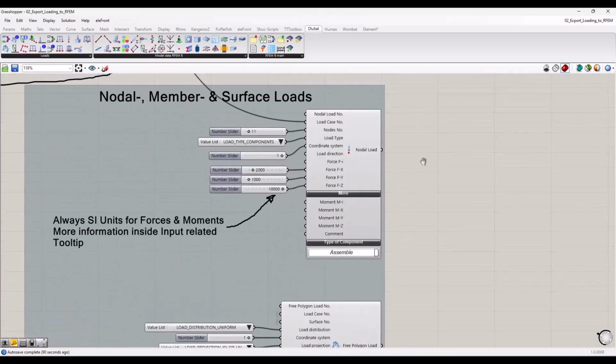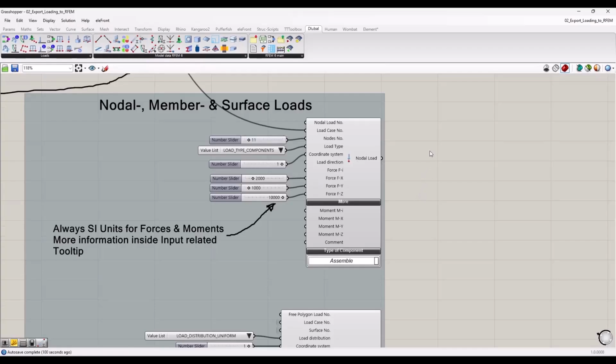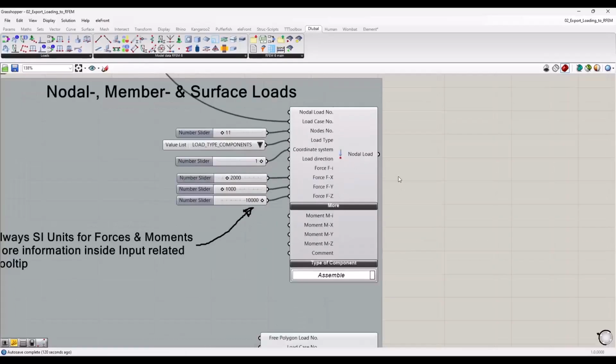I fill these load cases with loads, as I showed before. Here, maybe as a comment, any value that you input into our components is usually related to SI units. So meters, Newton, most common stuff. You cannot change these units into anything else. This transformation can be done via a little recalculation if required. You can easily use a multiplication component and assign the proper factor to convert a pound force into a kilonewton or SI related unit. So that can be done in Grasshopper.